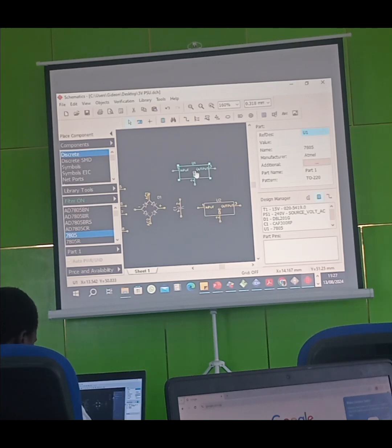It is when you start, before you convert to PCB, that you source for components. After you source for components, you start attaching the pattern to your existing schematic. You might have simulated the schematic on Proteus without having the components already. After you simulate it and see that this circuit is working fine on Proteus, that's when you start finding equivalent components.